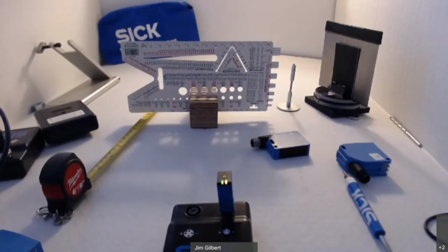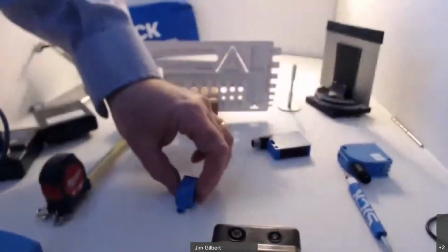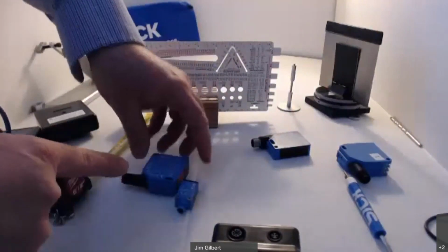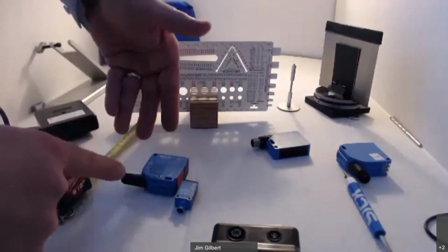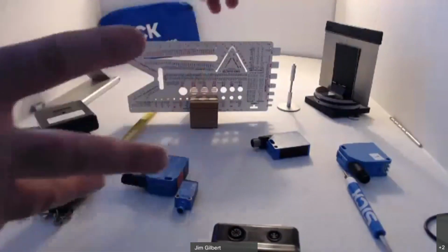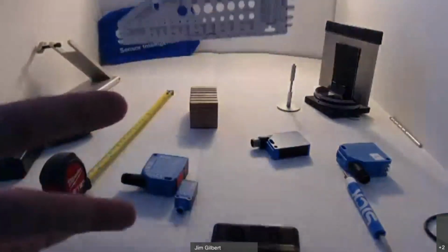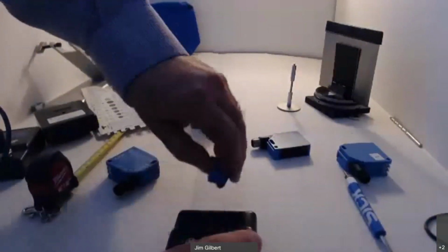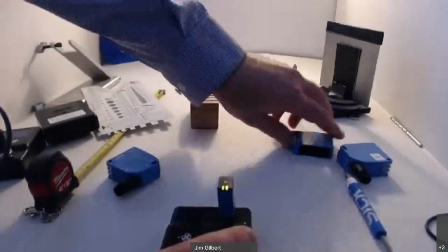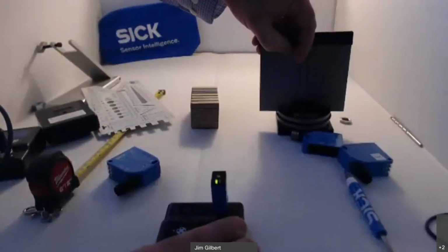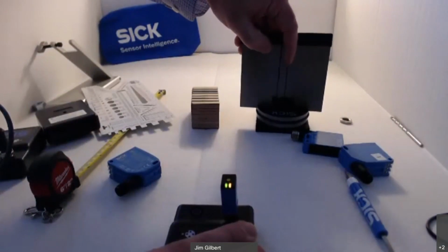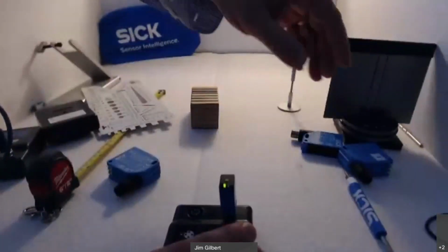Despite the challenges that I had with the setup, what I would recommend for small hole detection would be this WTT4SL, and also this WTT12 precision shiny laser. These would be really good at hole detection, and the same would be true for edge detection. Let's say the application was not sensing a hole, but sensing when the laser or the sensor first sees a target as it slides into place. Both of these sensors would be very good for that.